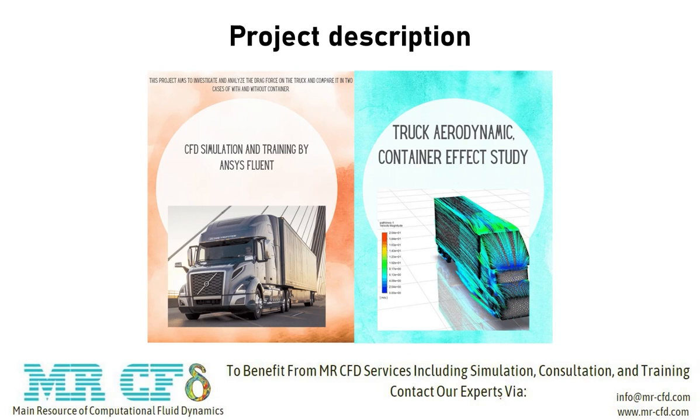We will discuss y plus values, pressure distribution over the surface of the truck, the velocity of the airflow around it, and of course, calculating the drag and lift forces that are exerted over the surface of the truck due to the passing of airflow over its surface.